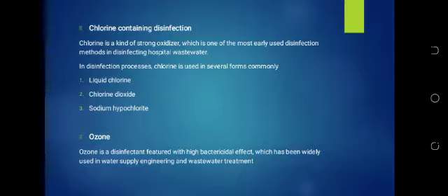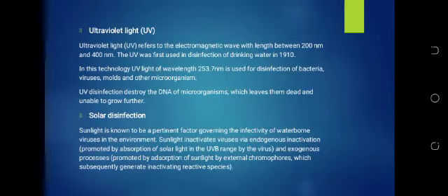In disinfection processes, chlorine is used in several forms, commonly liquid chlorine, chlorine dioxide, and sodium hypochlorite. Ozone. Ozone is a disinfectant featured with high bactericidal effect, which has been widely used in water supply engineering and wastewater treatment. Ultraviolet light,